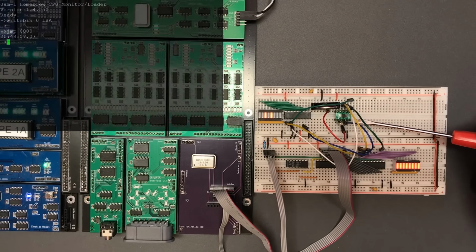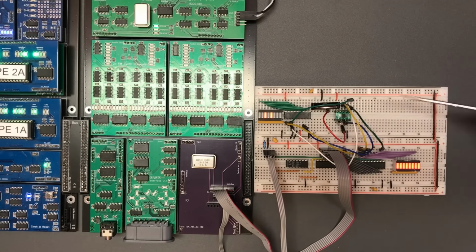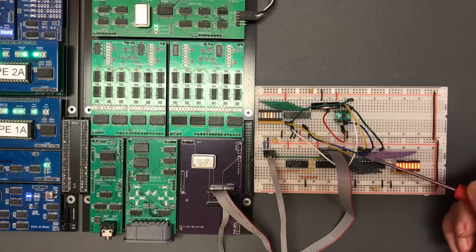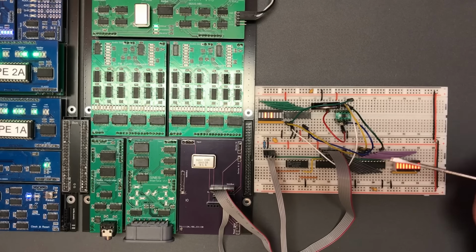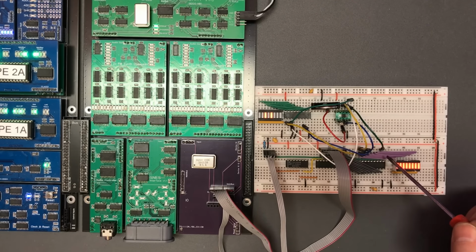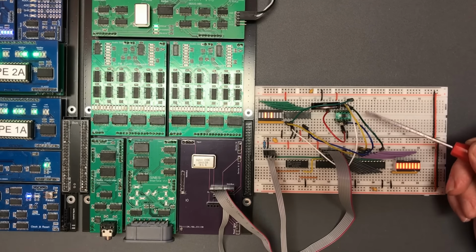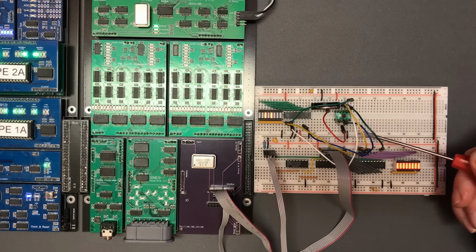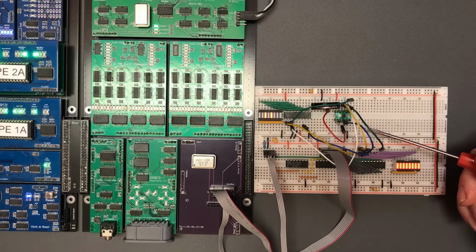Now, each of these SPI devices is connected up by 4 lines plus power and ground. Firstly, you've got the chip select line. We've got a different one of those going to each device, but then we have common lines, which are the clock, data in, and data out. And I think those 4 signals are a good way to separate out the functionality as we try and build bits of circuitry to help us along.